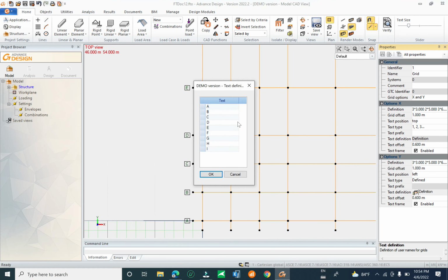Now I click on the create circle, input the center of the circle. Now we click on the center, and after that you have to input the radius. Now the radius I take it 2 meter for the radius, not for the diameter. This one for the radius of the circle, and you input the number of sides.